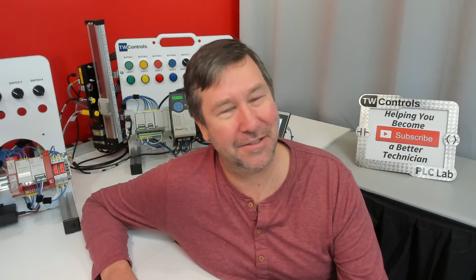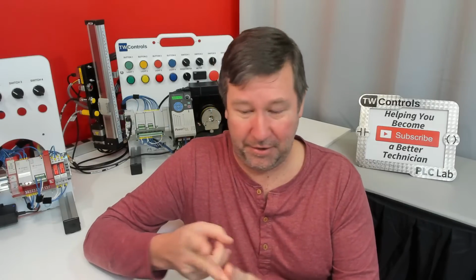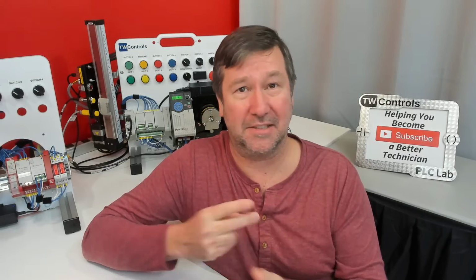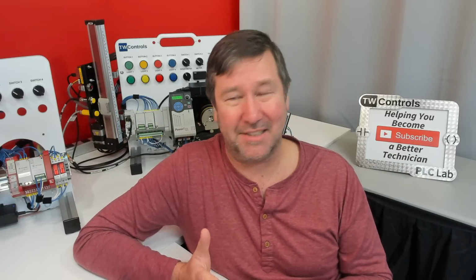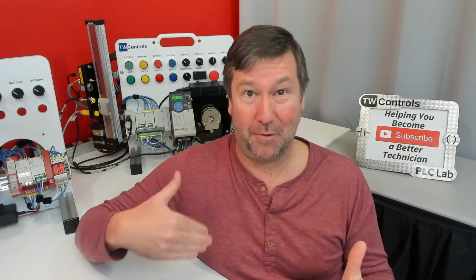I used to say, well, all you've got to know is: are you doing 24 volt? Are you doing 120 volt? Is it sinking? Is it sourcing? And you're done. But now that's a much broader question because now we have IO-Link and all this stuff, and the shorter we can make the run of wire on a machine, the better off we are.